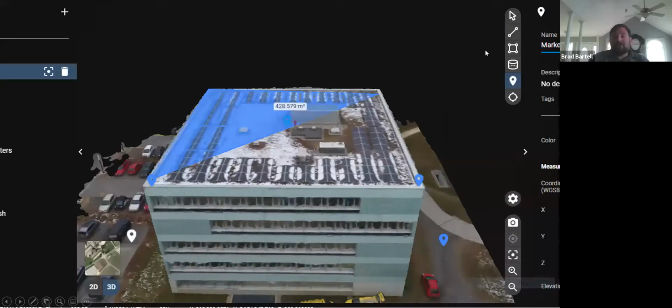So this is showing from our software, you can draw right off the top on that. You just click right on the photo, bring it in, and you're drawing. It's geo-referenced. You can take the measurements right out, stick it in the CAD, and you're good to go. Basically, the same thing we're doing with the scanning, you can do with the drone. The reason I keep saying scanning is because as I get further into this, it's a really good mix of drone and scanning, and we can take a complete site and give you a nice 3D model of it, which we've already been doing.